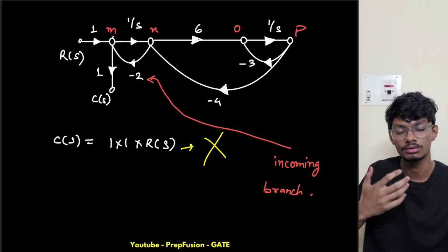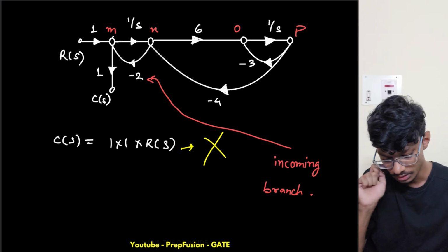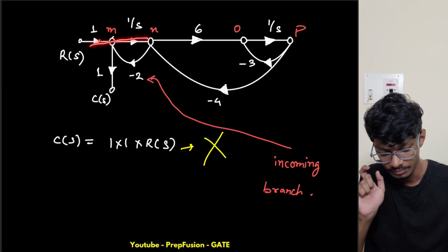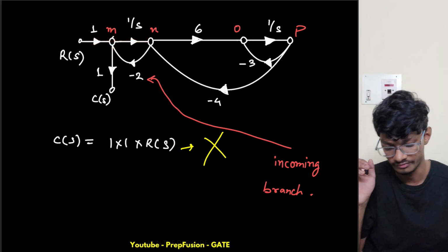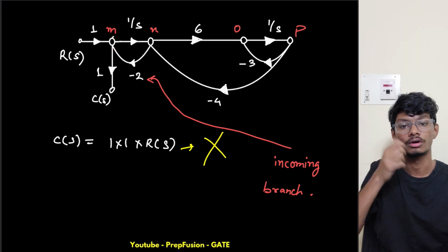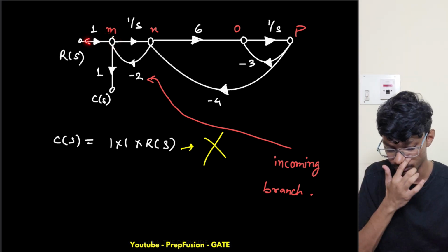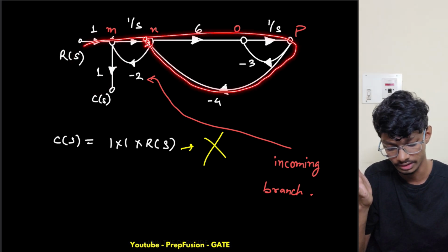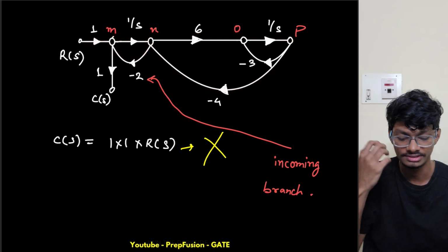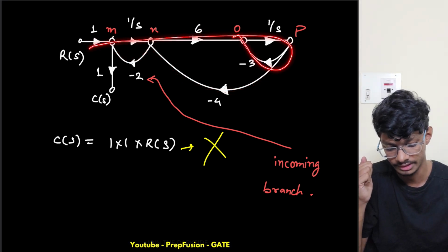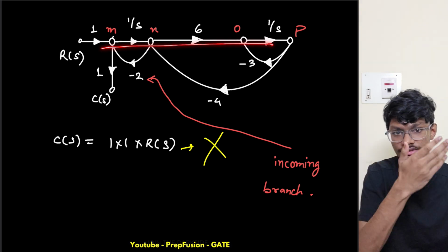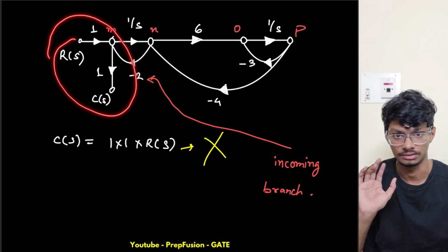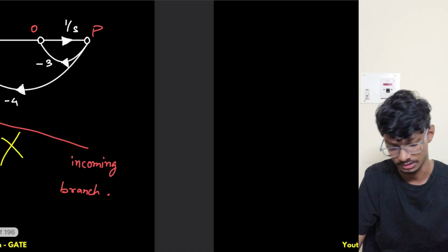So how many forward paths do we have? I see one forward path here. Now if I try to go through here, I have to again pass through here. If I get back somehow, I have to again pass through here. So the non-repeated nodes are 1 only, so we have only one forward path, right? Else I can come back here again, I'm repeating node N, node M, so this isn't a forward path. Or I can go there, again I'm repeating node O. I've already passed through this. I can't again pass through this node. So we have only one forward path. So that thing is correct.